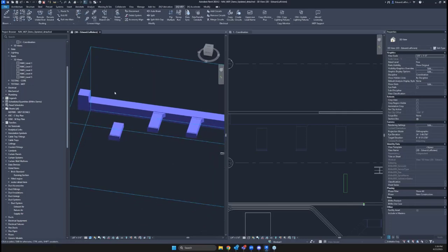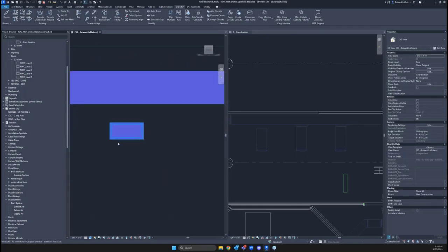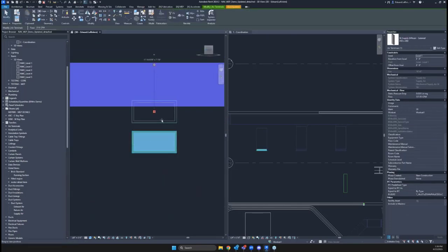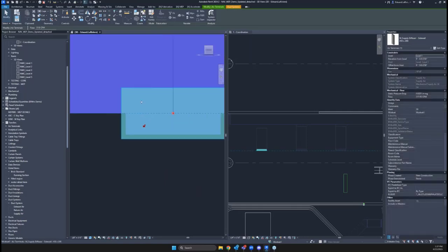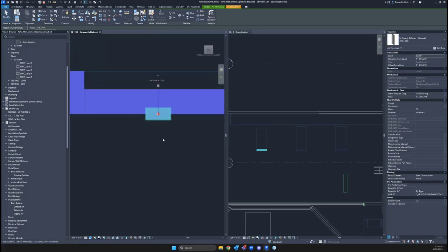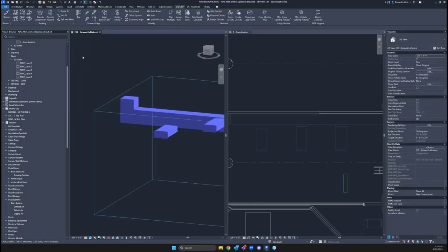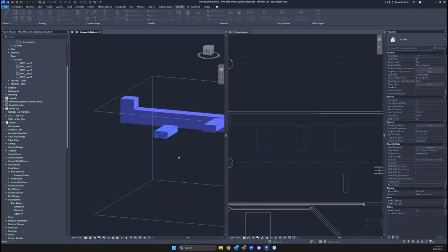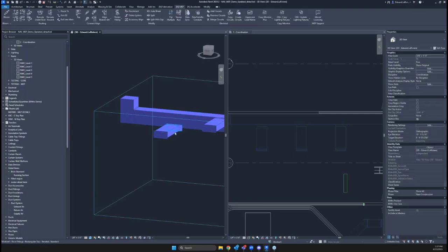That tap tool is actually a whole lot more powerful than I just made it look. It's really built to help us with those situations where Revit doesn't like it, but we know it exists like that in real life. So I'm going to nudge this up exactly one nudge so that connector hits that face. Doesn't matter how much, it could be a fraction of an inch. That connector just has to hit that face, because that tap tool will allow us to make this connection, right?